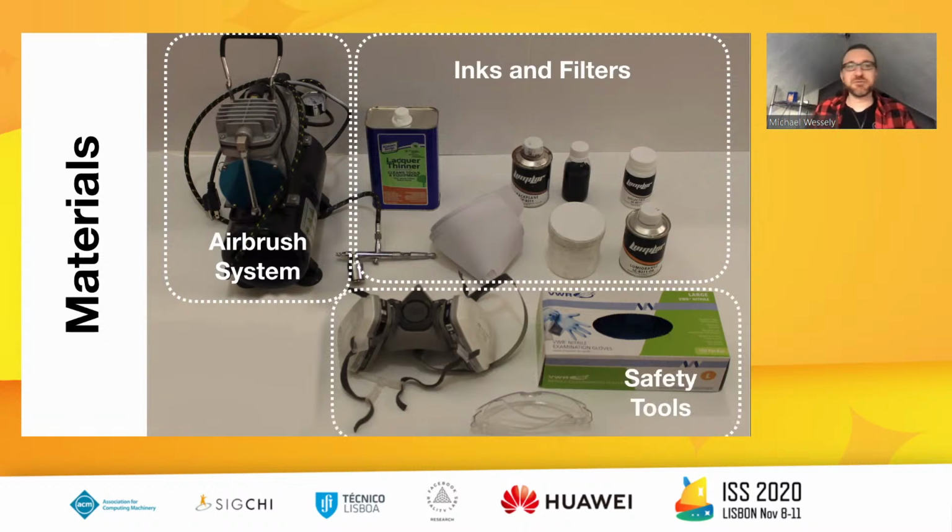And then, of course, most important, always when you work with these kinds of materials, is safety equipment. Since you're spraying, you're creating a fog that you can breathe in. So you should always wear a mask, you should wear safety glasses, and you should always wear safety gloves.